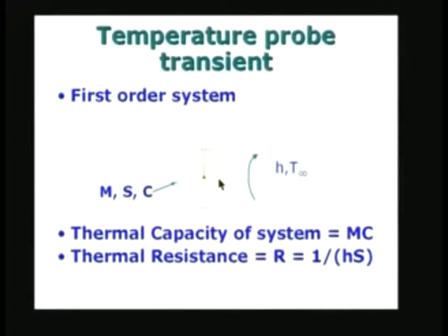The third case is where the temperature is actually varying periodically with respect to time, cyclically, in terms of a sinusoidal variation, and then I would like to find out how the system, the thermometer here, is going to respond to the changes or the variations in T infinity. We will see in a moment. I will work it out on the board.